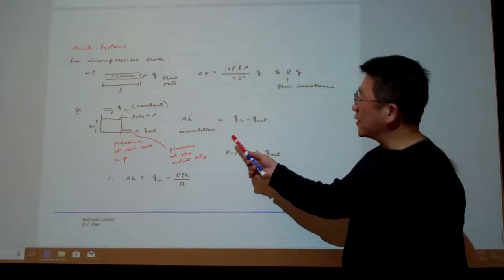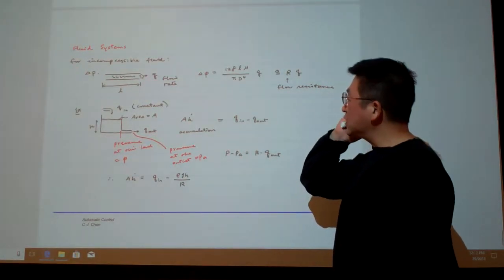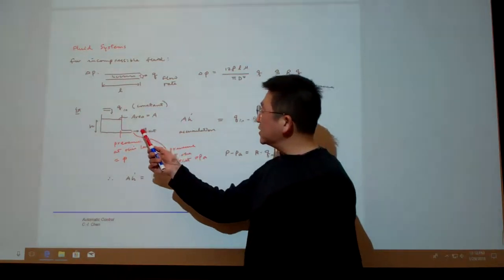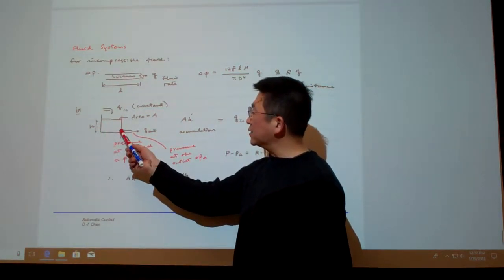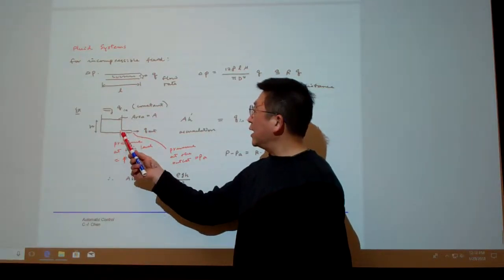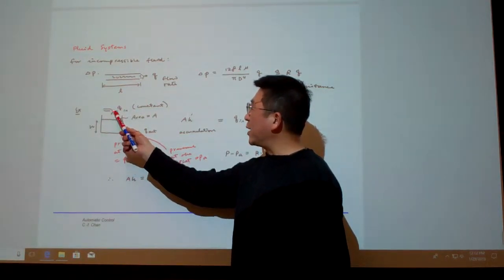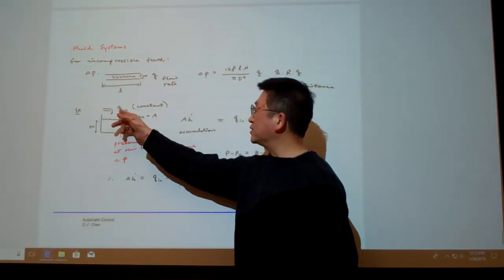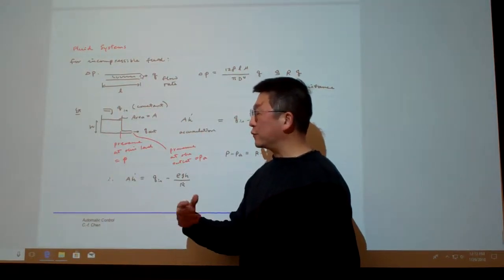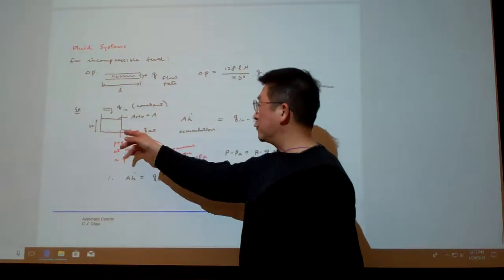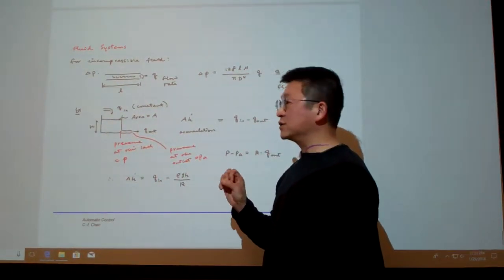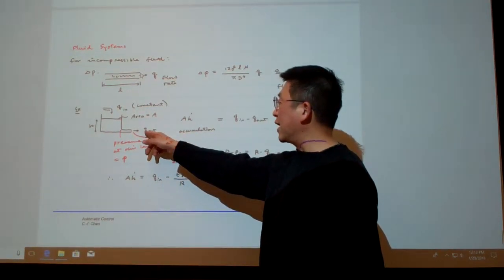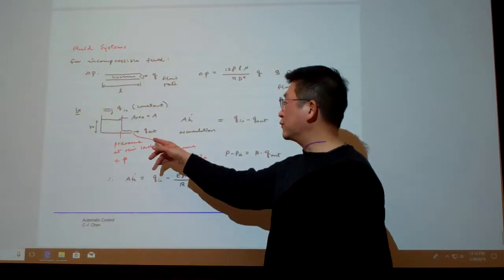We take this as one example here. See how can we model this system. This system basically here is this. We have containers, we have a reservoir, and reservoir is provided by a constant flow through a piping. So basically here we provide is a constant flow rate to supply this reservoir. And also at the outlet here we discharge this fluid, and by controlling into a constant discharge flow rate.